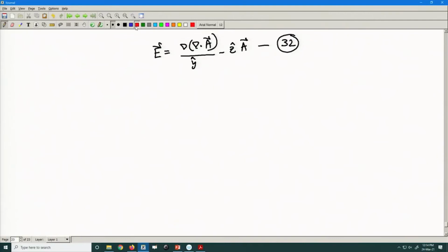Now, you can appreciate that once the vector potential A is found out, the electric field can be readily found out. So, the main step in Helmholtz equation is finding out the magnetic vector potential given the current source J under the given boundary conditions surrounding the problem and surrounding Helmholtz equation.